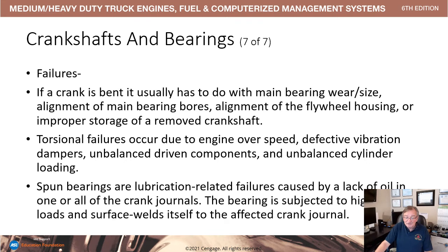Failures: if the crank is bent, you're going to have a failure at the balancing lobes and the journals for the connecting rod. Torsional failures occur from engines being oversped or running away, or a vibration damper going out of balance, so crankshafts can actually break.